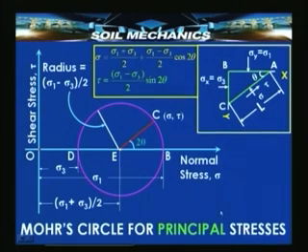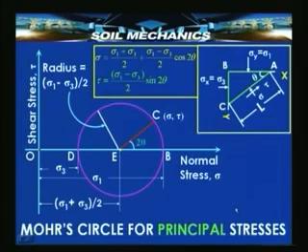So, looking at this slide, we can see that there is a minor difference between general sets of stresses and principal stresses. The difference is that when there are principal stresses acting on the known planes, there are no shear stresses, and to that extent the plotting of the Mohr circle becomes a little easier, and computation of the stresses on the plane AC also becomes a little easier. Now, do we really need a geometrical method for determining the stresses?